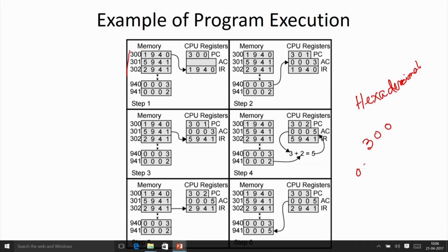I know that this is 0011 0000 0000. This is the exact address representation of the memory location; it is 300 in hexadecimal, but in binary representation it is 0011 0000 0000. So, it has a total of 12 bits. So, the address size of this particular memory unit is 12 bits, and we can now access those memory locations.